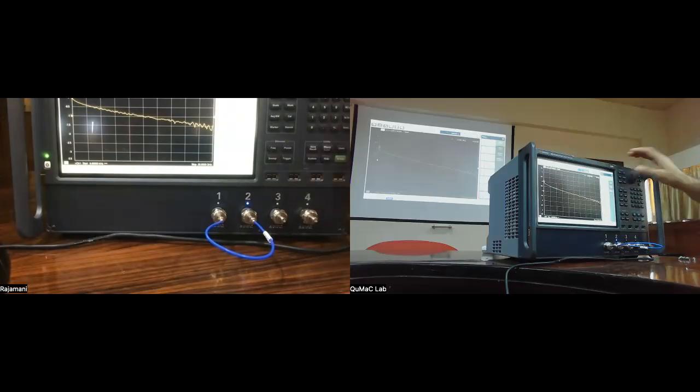And what you expect to see is very, very low attenuation at very low frequencies, because the loss in these transmission lines is often frequency dependent, which is what you're seeing here. And then slowly it increases. And at about 20 gigahertz, we have about 1.5 dB of loss. Okay. Now, this 1.5 dB, what you're measuring as transmission, could be due to two factors.